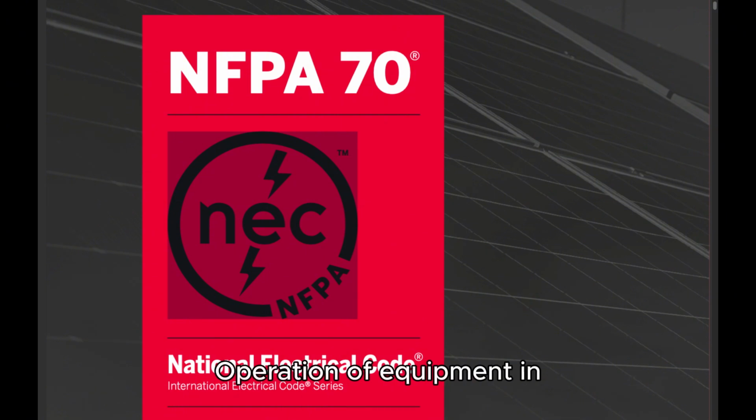CMP10 Overload. Operation of equipment in excess of normal full load rating, or of a conductor in excess of rated ampacity that, when it persists for a sufficient length of time, would cause damage or dangerous overheating. A fault, such as a short circuit or ground fault, is not an overload.